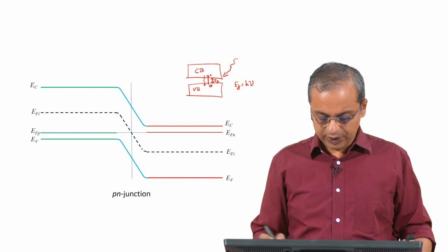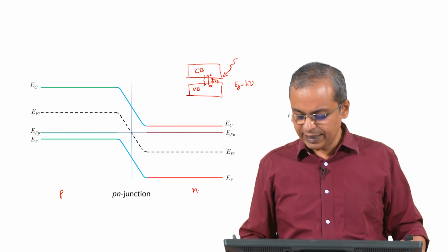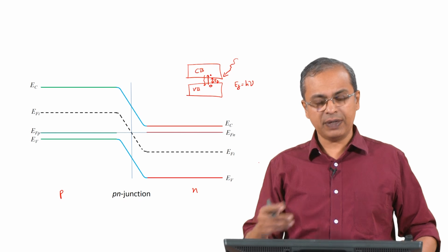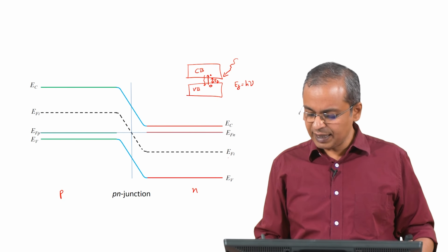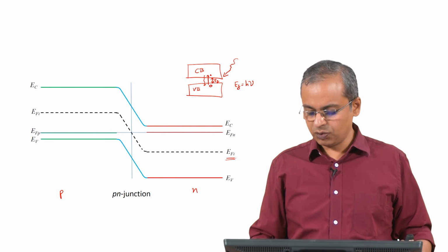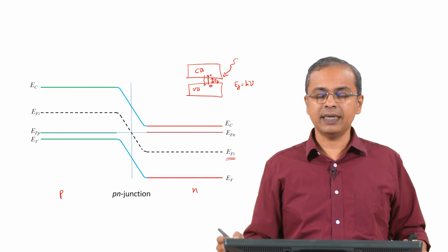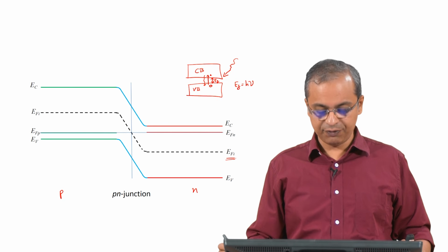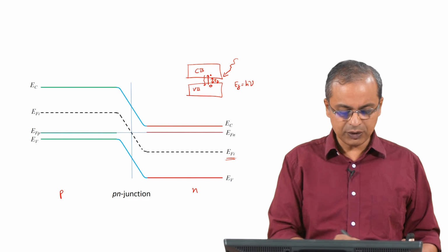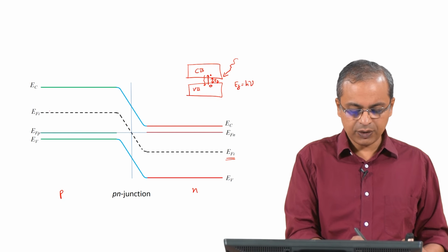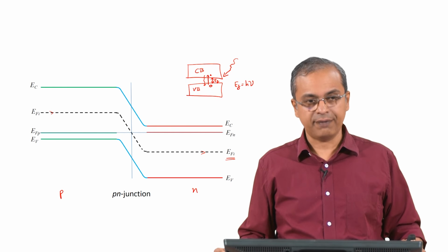So, we looked at it as again the same thing, a p-n junction. This is the p side, this is the n side. For both these samples, assuming that we started with the same semiconducting material, their original intrinsic Fermi energy, which I am calling E subscript F, with subscript I saying that it is the intrinsic Fermi energy, is the Fermi energy of that material if it had no dopants, was this particular value. So, that is the value that you see here.